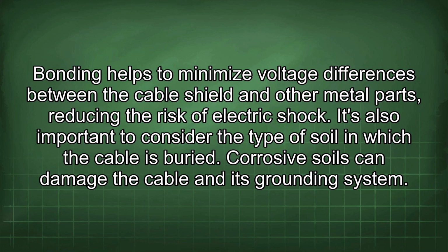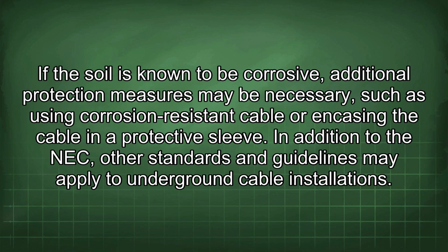It's also important to consider the type of soil in which the cable is buried. Corrosive soils can damage the cable and its grounding system. If the soil is known to be corrosive, additional protection measures may be necessary, such as using corrosion-resistant cable or encasing the cable in a protective sleeve. In addition to the NEC, other standards and guidelines may apply to underground cable installations.